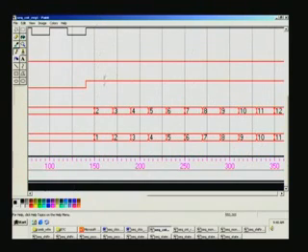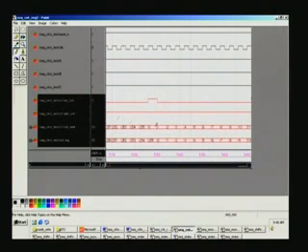If you have a look, there will be a clock pulse here, so the rising edge of the clock pulse here, and once again it will rise here. Again you can see at all points of time this counter next is pre-incremented here. Going to the next waveform, which is a continuation of this, once again you can rest assured that all the other points were clearly counting, and what is shown here is a snapshot of the end point. So when it is approaching 255, what happens, that's what matters, and being offline in the waveform view, I think it would be better to have start and end point.